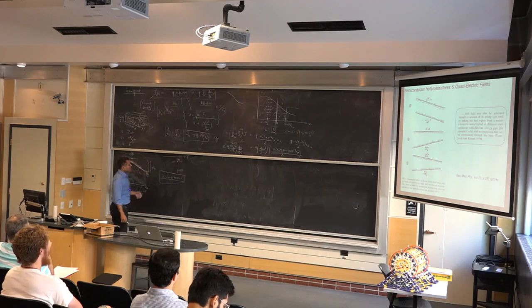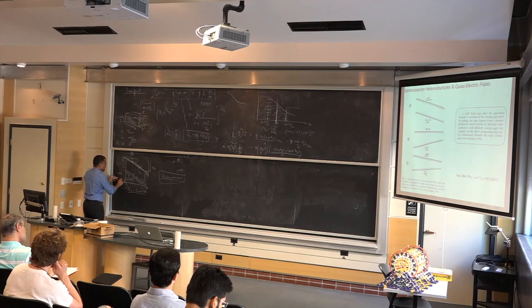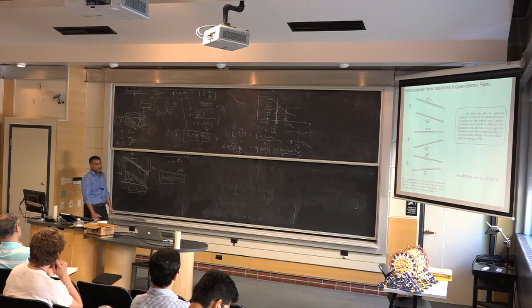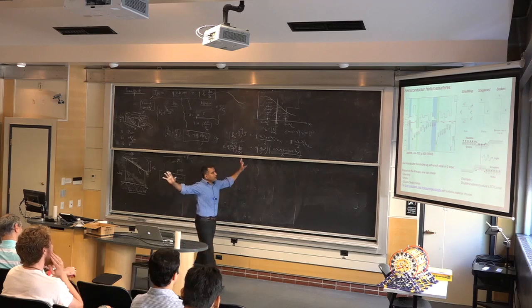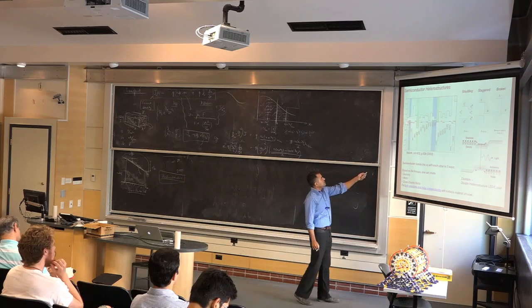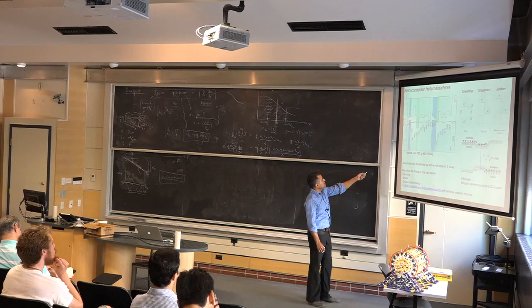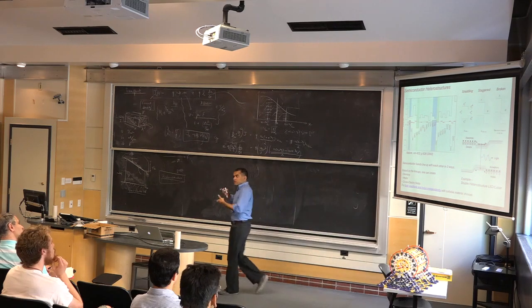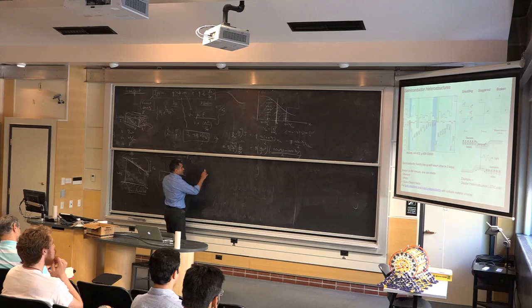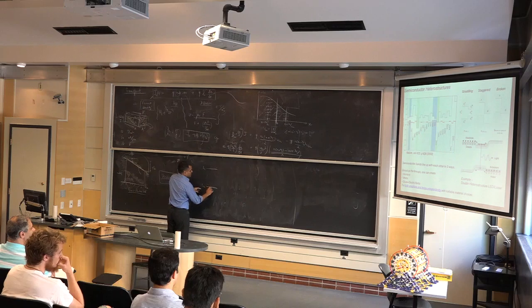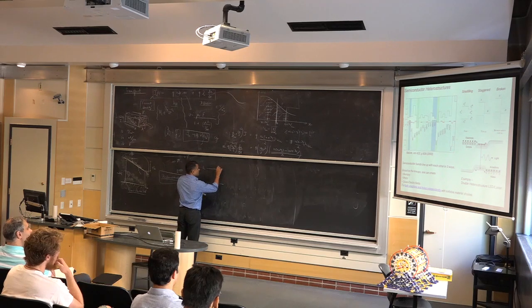And to create these structures, you need a large range of semiconductors with different band gaps and alignments and that sort of thing. So that article is kind of nice, you can read up. So we have a very wide range of semiconductors. You have silicon, germanium. You can see now the bands are such that silicon is here, germanium valence band is here, conduction band of germanium is here, conduction band of silicon is here. So if you create an abrupt junction between silicon and germanium, then it will look like this. So I have conduction band of silicon, valence band of silicon, and then germanium looks like this, right?